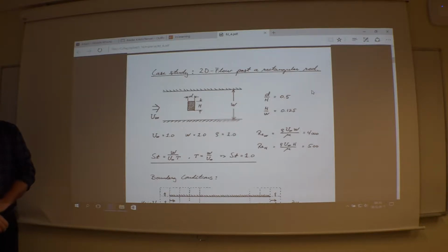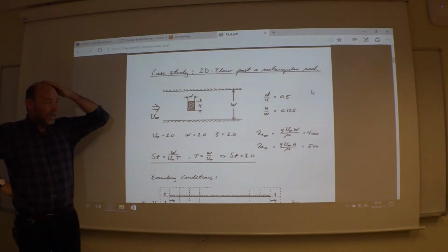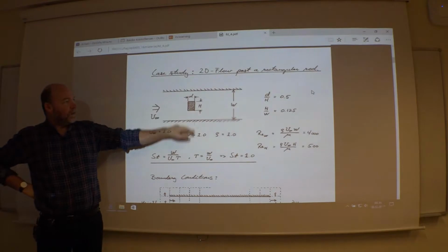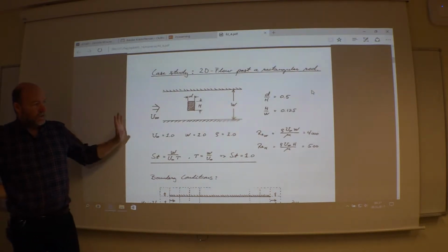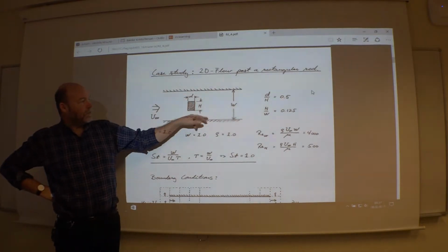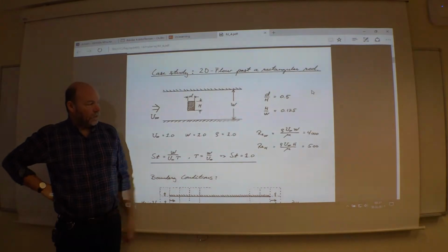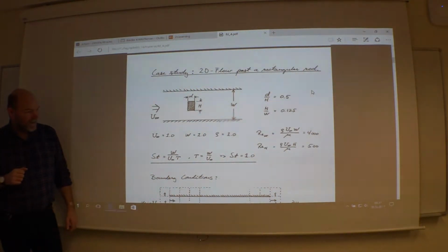The case, which actually you should be able to program yourself, you have the MATLAB code, is sending in a constant flow and hitting sort of a rectangular object here, and then a choice of proper Reynolds number. You should get this nice von Karman vortices, alternating shedding from this blunt object.